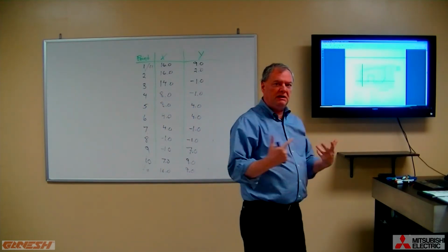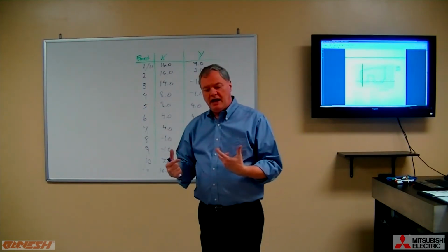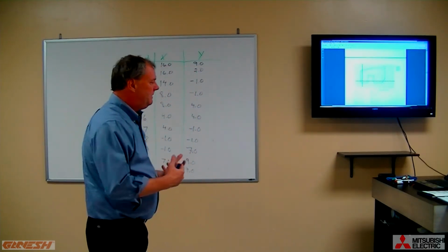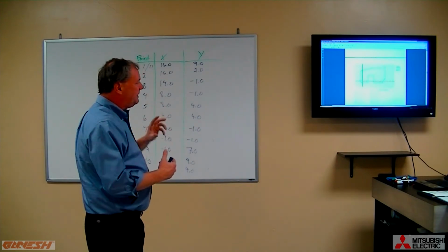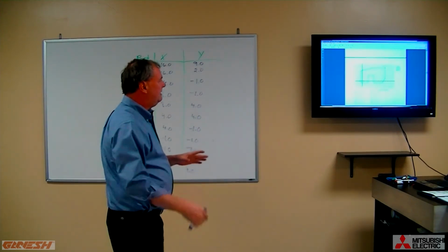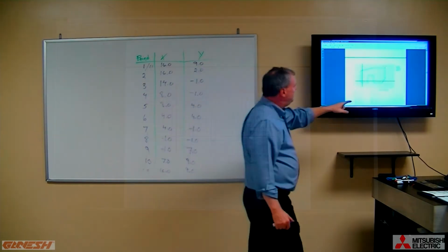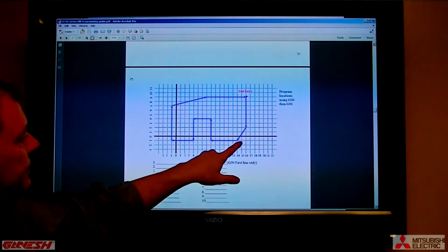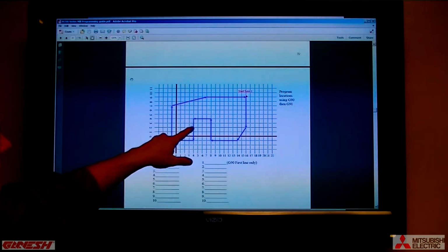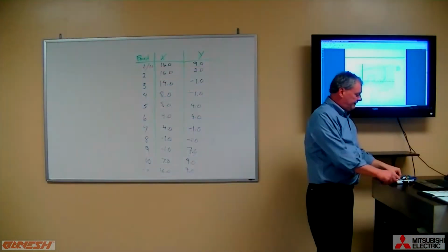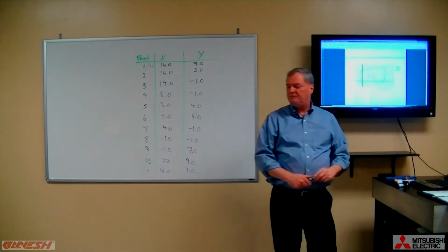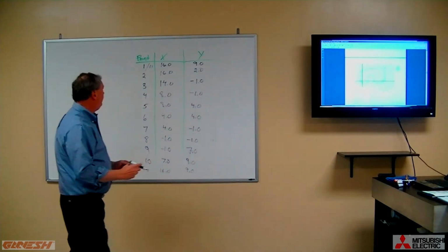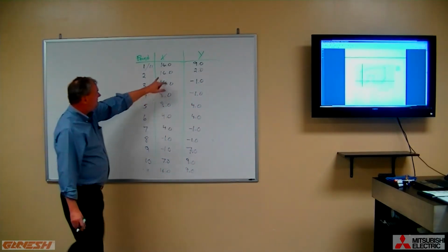We talked about milling as a process, and to make your first NC program, using this data is really as simple as first doing exactly what we've done, just identifying the locations that we want our cutter to move in terms of x and y coordinate pairs. And if we want to make this an NC program, it's very simple. All we need to do is use these numbers,